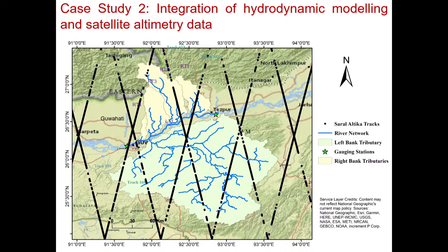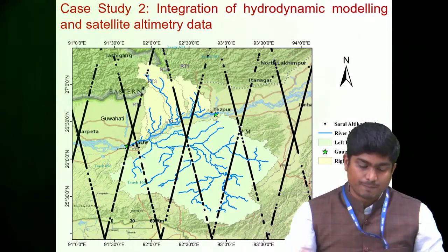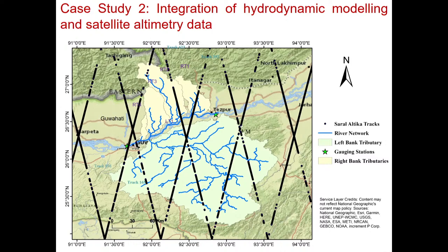But over a period of time, you can see that it is very costly to monitor in situ gauging stations. Sometimes you have complete in situ observations, meaning gauging sites for that particular river, but you may not get the density you are looking for, or sometimes you don't get data at all. Maybe that basin is completely ungauged or sparsely gauged. So in that case, people are now working on how space-observed data, of which you have an abundant amount, can be utilized to establish a virtual gauging network where you can monitor the water level and the discharge. That is what we tried to aim for in this particular case study. So again I will repeat.